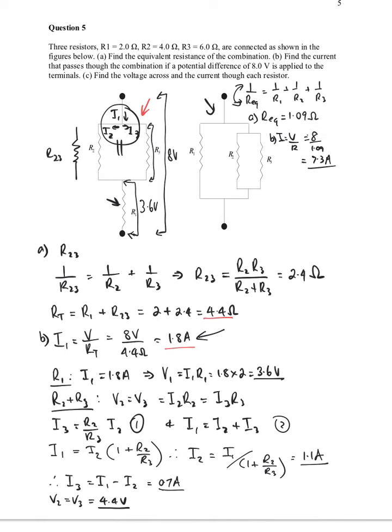Now, when you know that the voltage drop across each one of these is equal, okay, so there's the same voltage drop across all those, they're in parallel, then what you end up with is that I1 is equal to 4 amps, I2 equals 2 amps, and I3 equals 1.3 amps. That works out nicely. All of these guys add up to this, so the current is flowing correctly.